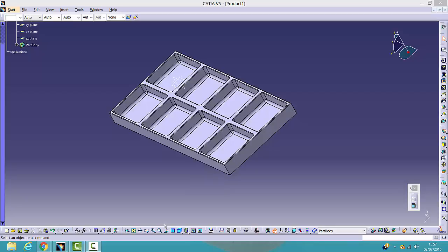In this episode what we're going to be covering is modelling an ice cube tray similar to what you see on the screen here. And we're going to be using pattern and mirror methods. Now Catia allows you to define 3 types of patterns: rectangular, circular and user patterns. These features accelerate the creation process. So say if you've got one object, half of an object that you've built, you can then replicate that using symmetry into another part of that object. So let's get straight to it.